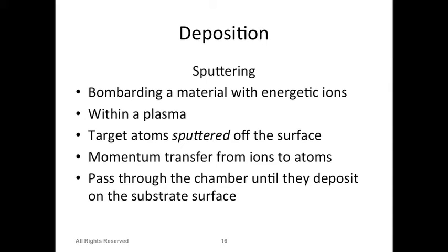But when we put some copper, 4% copper or 3% copper in there to make an alloy, then it actually helps to reduce the electromigration issues sometimes. And there are alloys which are used for a lot of applications. So for that, copper has a melting temperature of more than 1000 degrees centigrade, I think 1024, and aluminum is 660 degrees centigrade. So we cannot use those two materials in an E-beam or thermal evaporator, right? Because they have different melting temperatures.